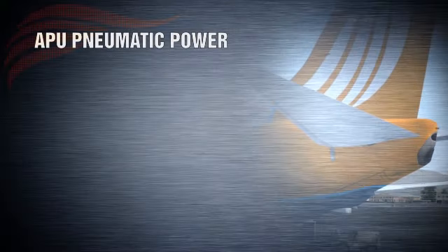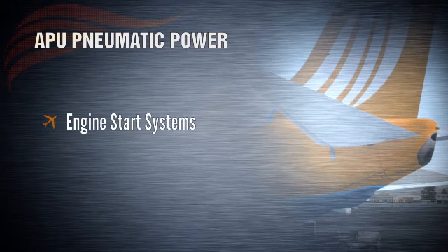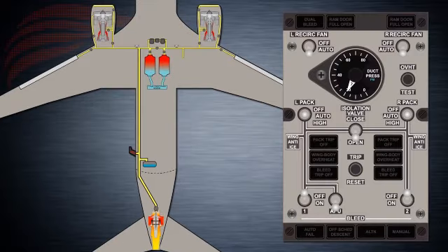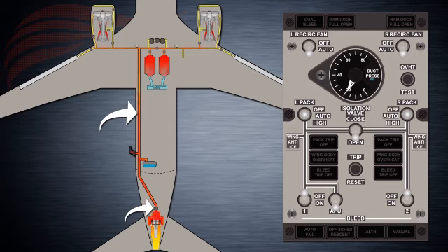The APU does not power all the systems that require bleed air we mentioned earlier in this lesson, such as the anti-ice system or the hydraulic reservoirs. It only supplies bleed air to the engine start systems and the cabin pressurization and thermal control. Just like with the engines, the APU has an APU bleed air duct that collects the extracted bleed air from the APU bleed air valve and ducts it into the aircraft's pneumatic manifold.